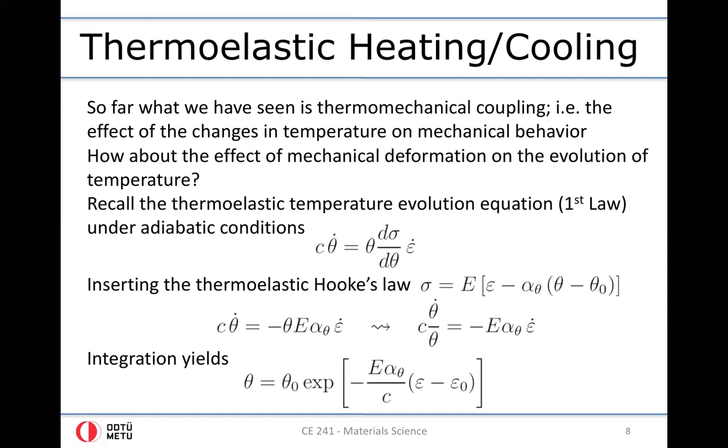That means if you compress the material, where the rate of the strain is negative, the rate of the temperature will be positive. In other words, temperature will increase. Or if you extend the specimen at a positive strain rate, then the rate of the temperature will be negative. Therefore, temperature will tend to decrease. So mathematically, you can actually show it very well.